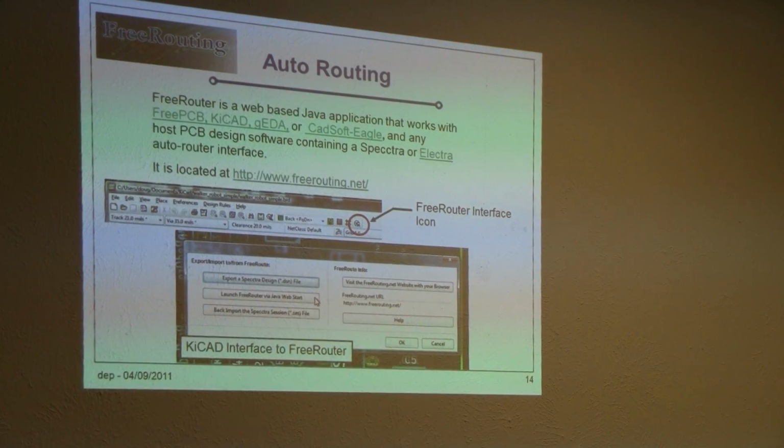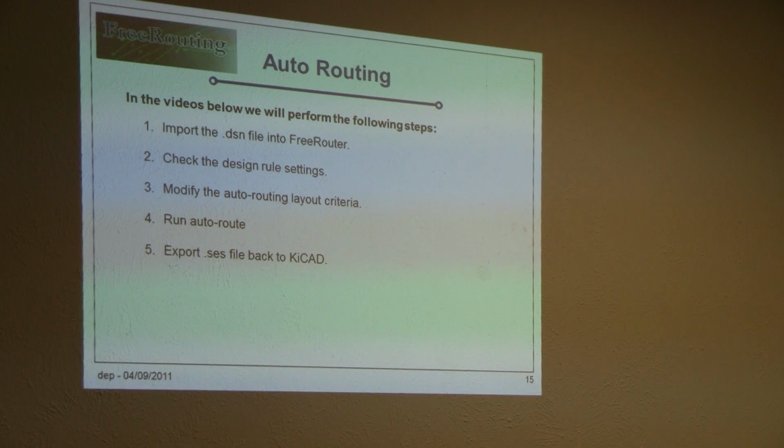Now, a question on the routing, which we didn't do. If you had a wide route, like really high power, what does it do on the corners? Does it miter them, round them, or keep them square? I know in KiCAD there are some options for that, and I believe there are some options in the auto router too.